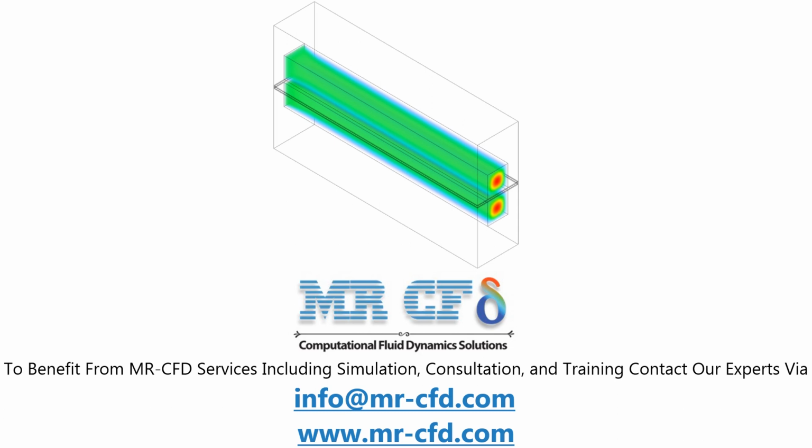The fuel cell used in this simulation is a type of polymer electrolyte membrane fuel cell. The model consists of two main cathode and anode segments, each of which has 4 layers, including a flow collector, a flow channel, a gas distribution area, and a catalytic section, and the space between the anode and cathode layers is filled by the polymer membrane.